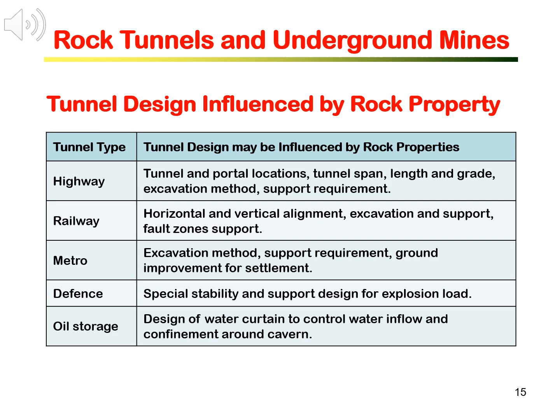For metro tunnels in urban areas, the biggest concern is ground settlement. Therefore, based on ground conditions, specifically rock mass quality and groundwater, we need to select appropriate excavation methods and the TBM type, and design support and ground improvement in order to control ground settlement.